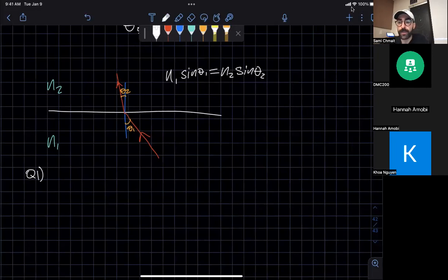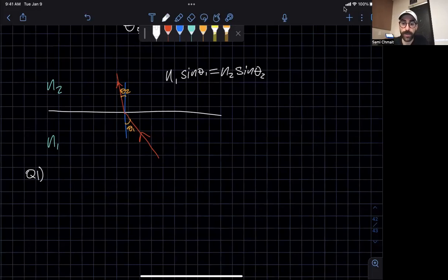Now, I'm going to say something that's very important to solving these questions when we're dealing with inductors. At steady state, the current is constant, and inductors act as wires. That means it's just flowing across freely. However, inductors act like an open switch immediately after closure. So therefore, if we consider, let me put the screenshot of the diagram into my document here.